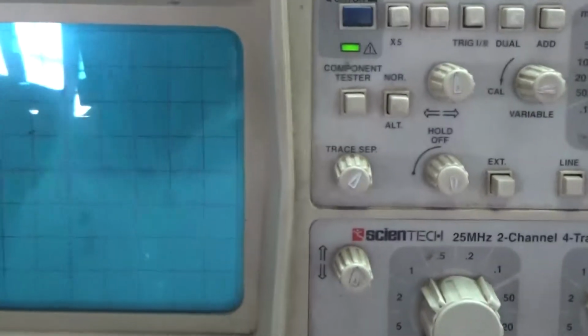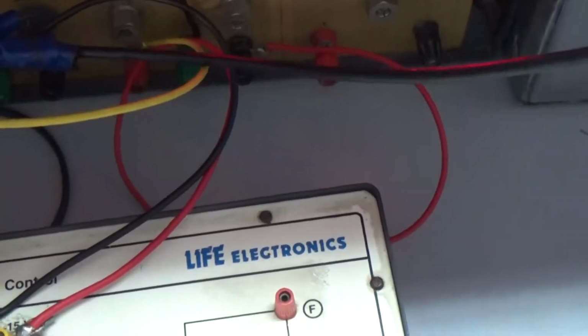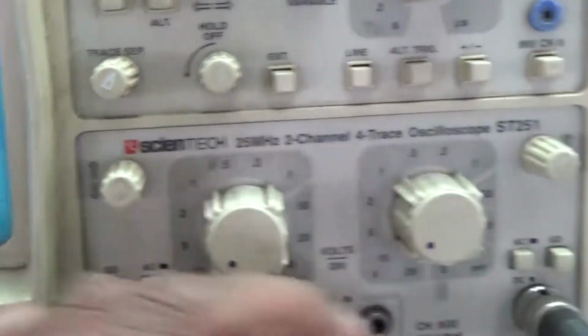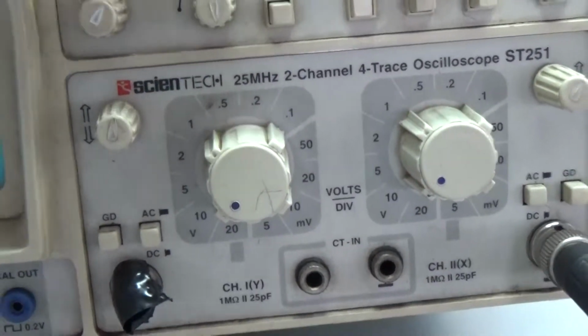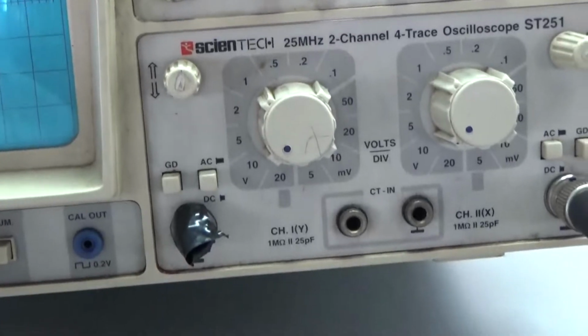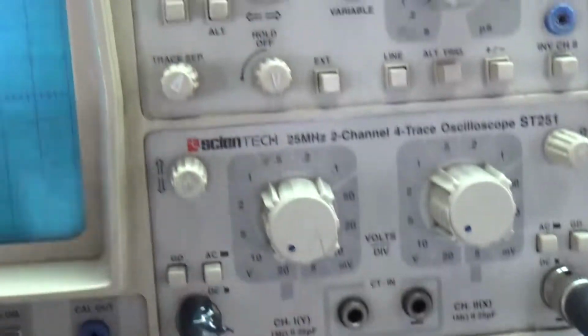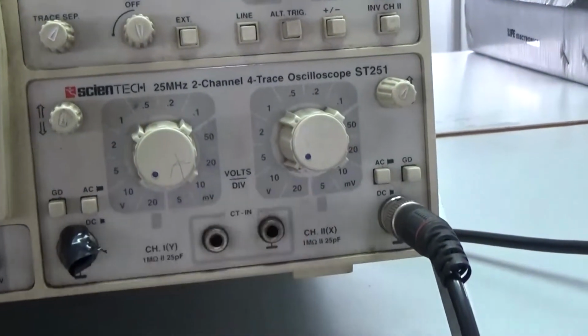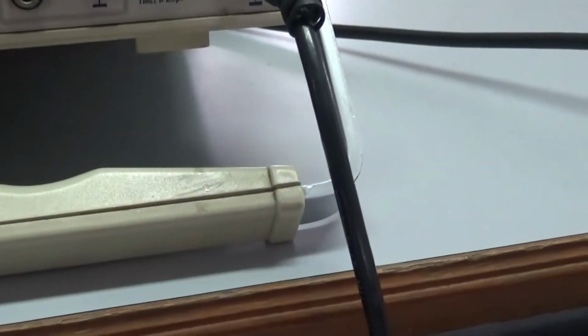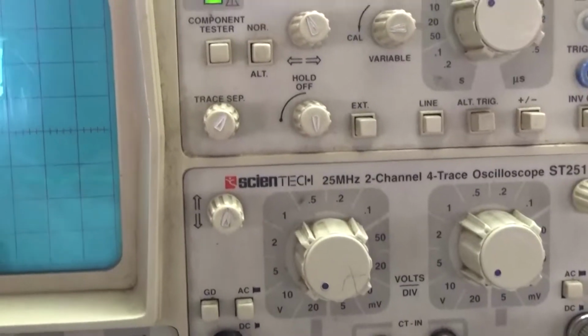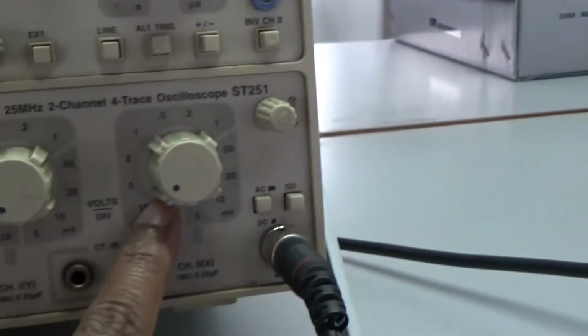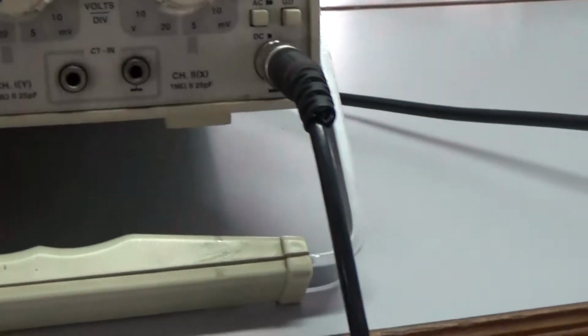Now let us see the voltage waveforms at different points. Now let me connect the CRO probe negative and 15 volt we are expecting to see there. So let me show you. It is showing around 1.3 into 10. Roughly 1.3 or 1.4 nearly. 1.4 into 10 is 14 volts we are getting DC. 14 volt you are getting DC and minus VDC again 1.4 into 10 is minus 14 volt. That's the DC voltage fed to the control circuit.